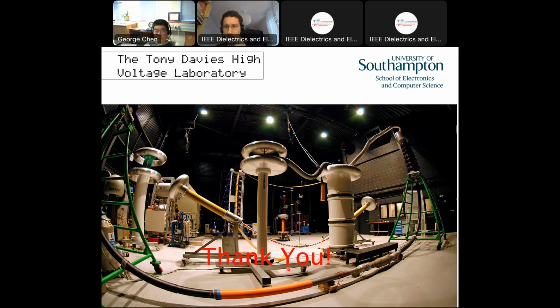Then we have another question here. I can see one was a more practical question that asked, how do you protect the measurement setup in case you measure up to breakdown of the sample? That's a very practical question. I think one of the good things with the PEA system is that when you have the breakdown, you probably simply trip the high voltage supply, and because the measurement system is isolated from the high voltage, it's all from the bottom electrode, which is earthed, you shouldn't have a major impact on your measurement system.